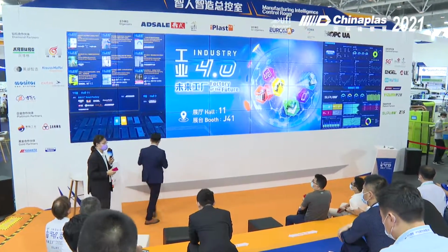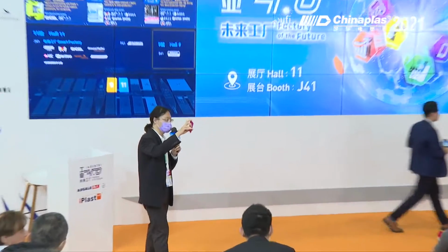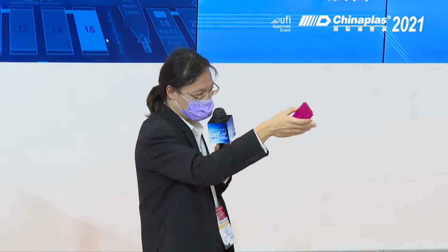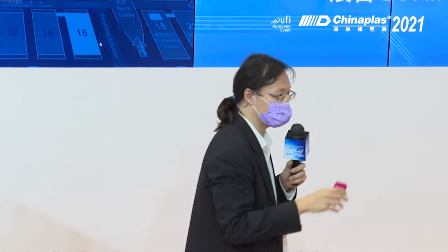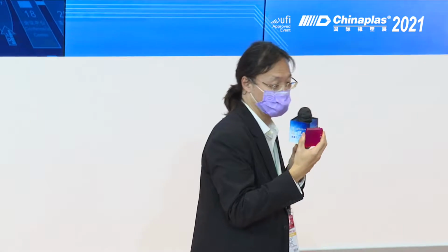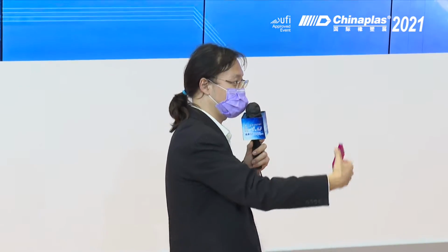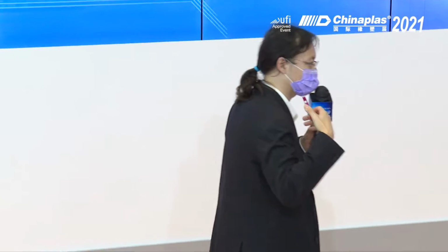Thank you. Actually, what I'm holding now is the first shot of today. So you have the rest from yesterday, and today we have the new color, the orange. But the benefit of Matsui's flow rate monitoring is that usually it takes like 20, 30 shots before we get a stable product. But using that mold temperature control unit and monitoring the flow, this is the first shot, and the second shot is already a good product. So it can save a lot of time when you change the mold, when you start a new production.